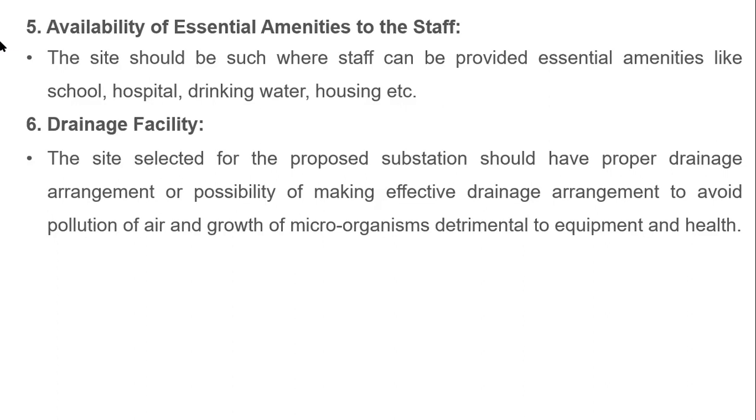While considering the land, we observe different considerations: whether it is near the load centers or not, and how much distance there is from the substation to the load centers; proper voltage regulation; whether incoming and outgoing transmission line feeders are available; whether there is enough space for future extension and forecasting of the substation; and minimizing the number of customers affected by service outages.